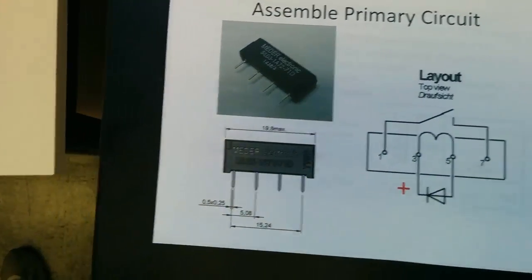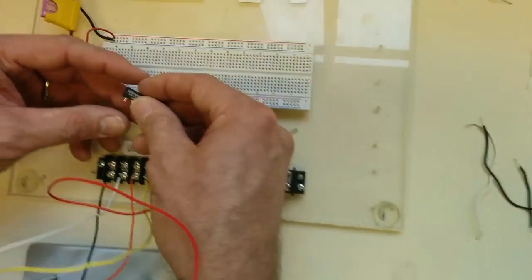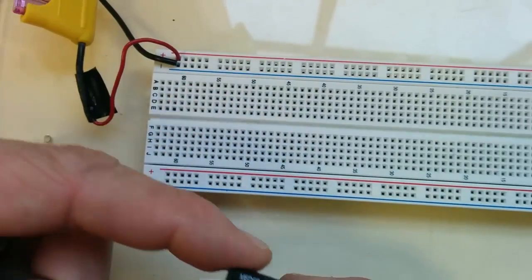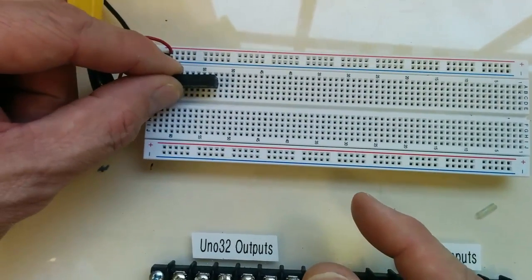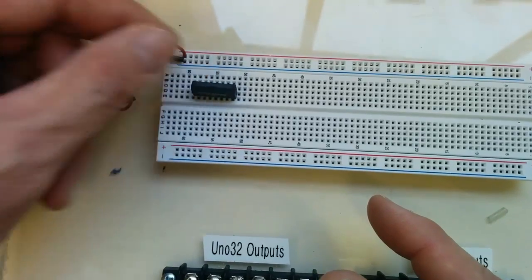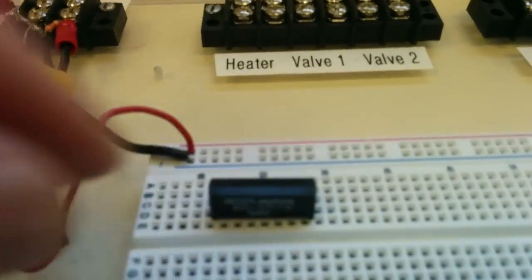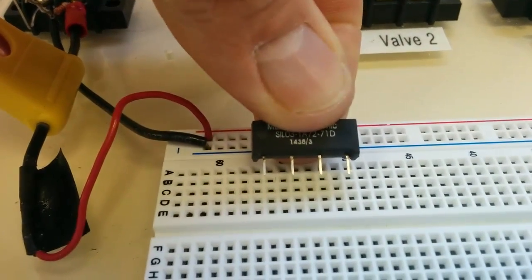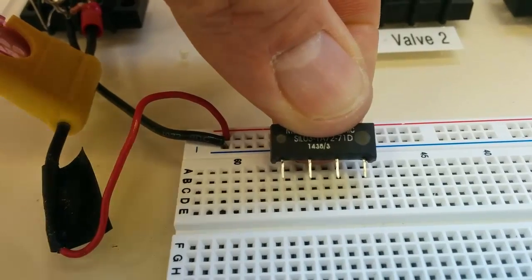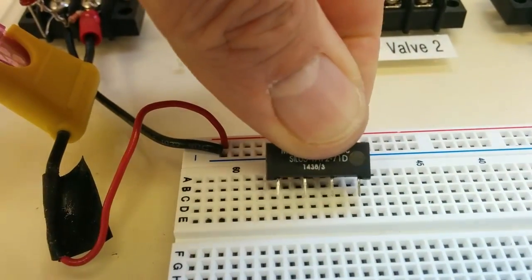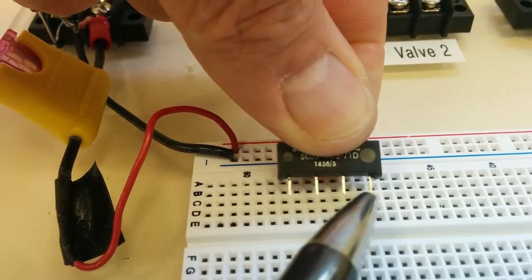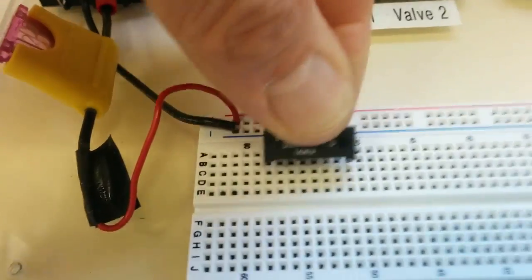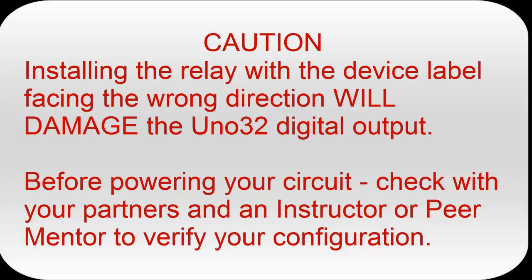All right, let's take a look at the wiring. Again, we've got our relay here, and we'll slide it in. It's going to have to be above the center line, so we're going to take it one step above the center line. And now we need to provide, if you look at it more closely, let me hold that up. You can see the pin on the left is 1, the second pin is 3, the third pin is 4, and 5, and then the last one is 7. Again, 1, 3, 5, and 7. All right, so we're going to go ahead and put that in here.